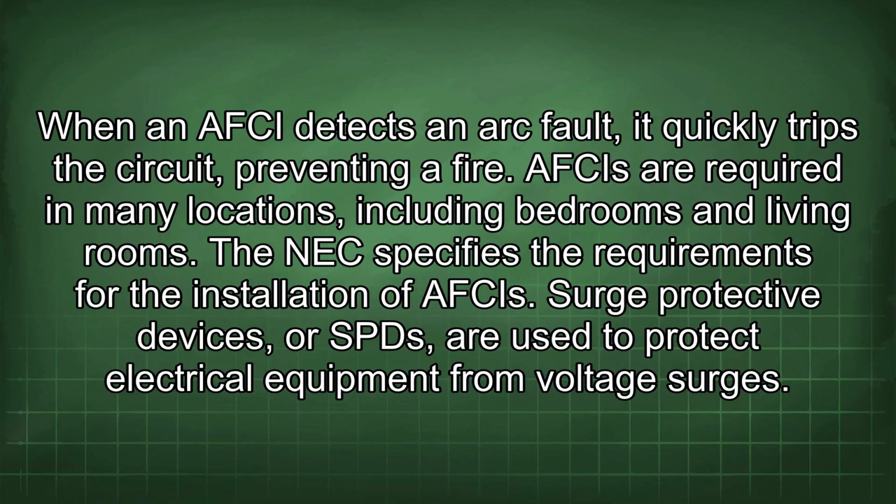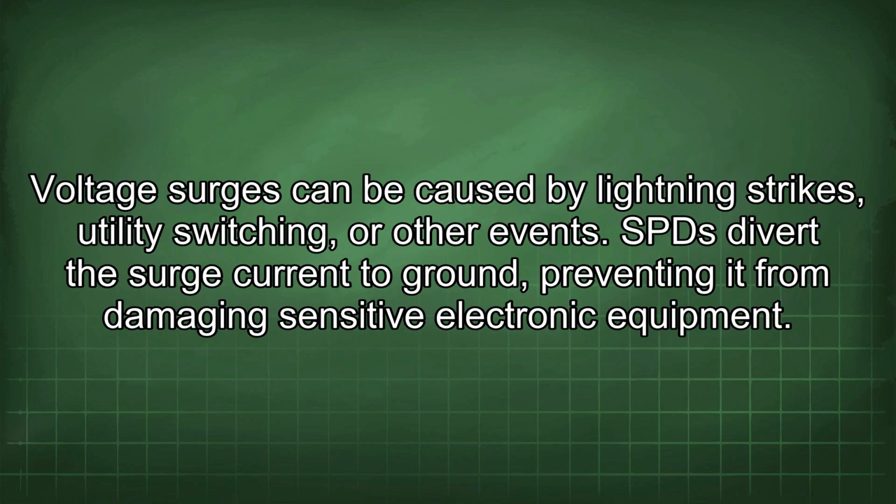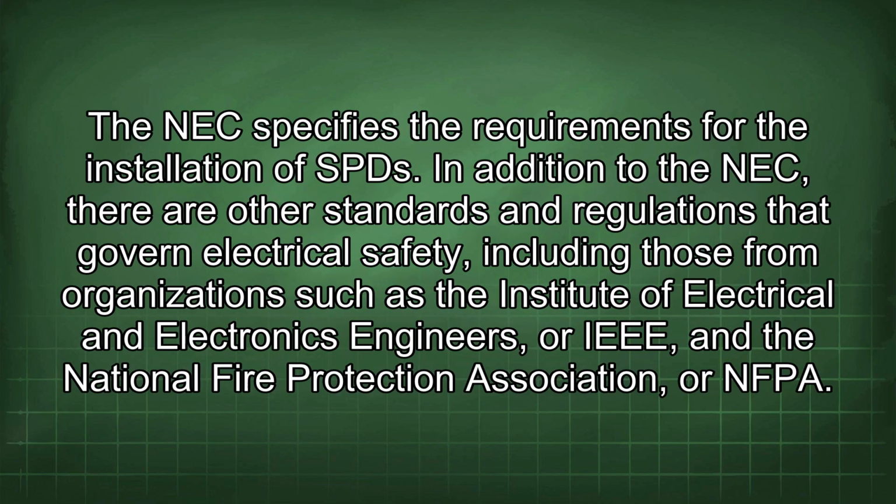Surge protective devices, or SPDs, are used to protect electrical equipment from voltage surges. Voltage surges can be caused by lightning strikes, utility switching, or other events. SPDs divert the surge current to ground, preventing it from damaging sensitive electronic equipment. The NEC specifies the requirements for the installation of SPDs.